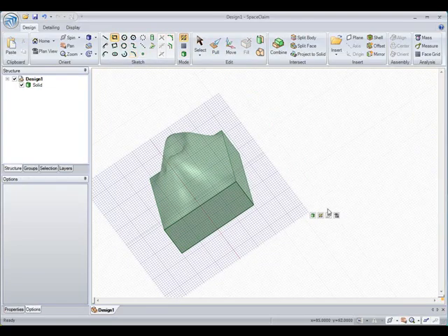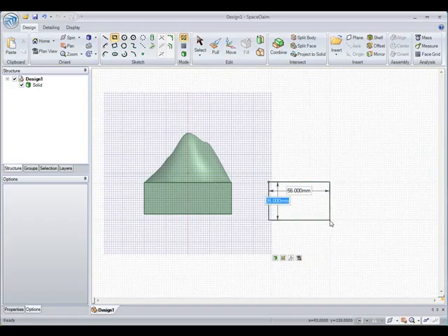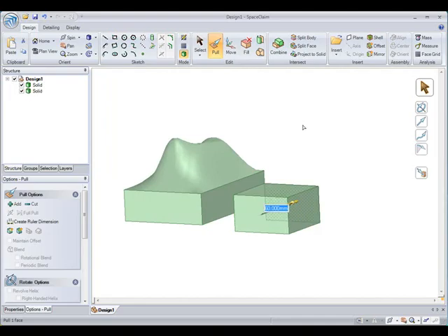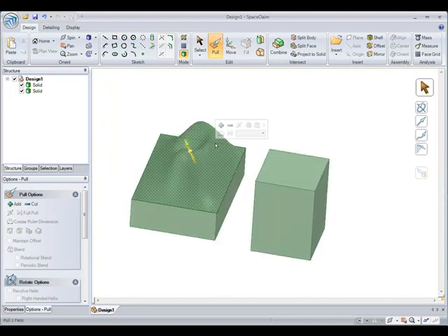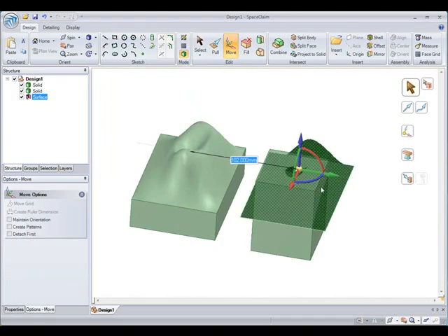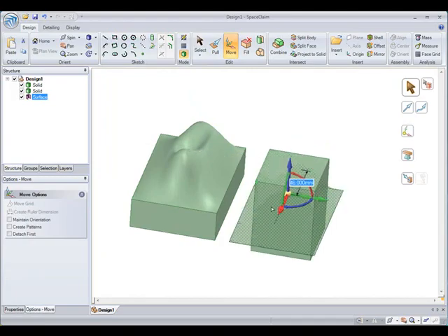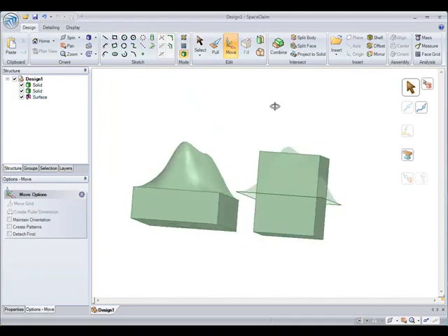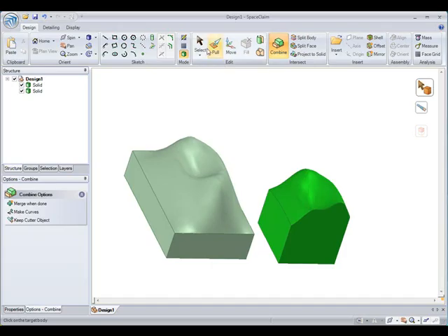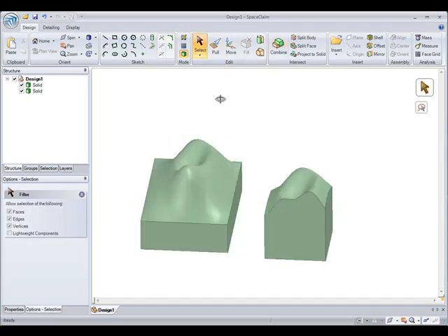So now there's also another way we could create blended surfaces, and maybe that's if we import a blended surface in to begin with. So let's say we have a solid block to start off with that I've just created, and I'll just copy and paste the surface back in, just with a Control-C, Control-V, and now I can bring it in as if I imported it, and I'll combine that surface with the solid, just by picking the solid and the surface, and now I've split that up and I have a nice contour on top of that.